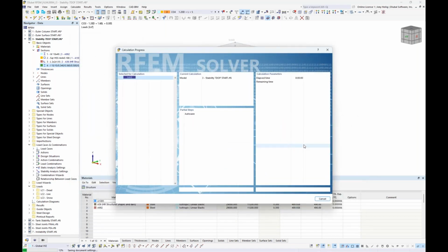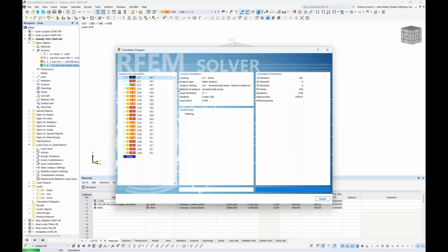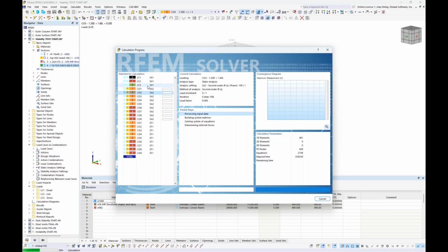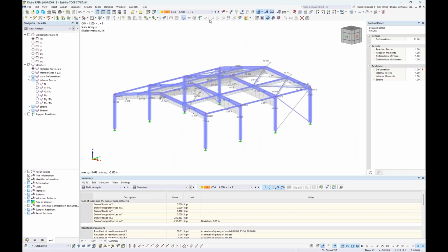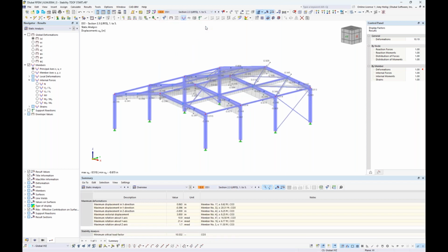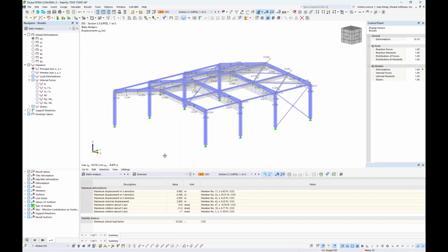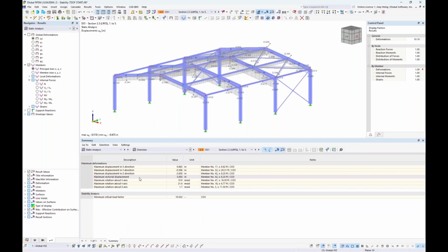So let us run through this calculation by running the Calculate All button. As we will see, we will first run through the load cases according to first order, our load combinations using a second order analysis, but then we run through all of those load combinations again for the structure stability. So when we toggle this drop down to the design situation for our factored load combinations, again, this is nice because it's more or less an envelope solution for the static analysis. But you'll notice within this table here that shows our static analysis results for this design situation, we have the stability analysis envelope solution as well.